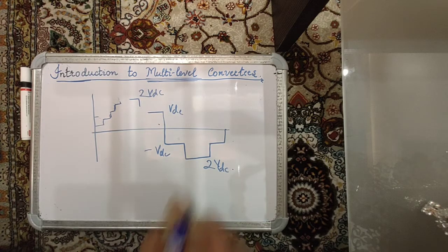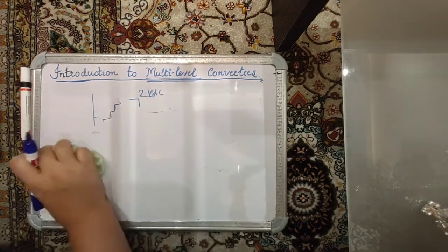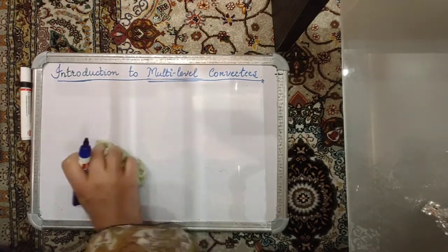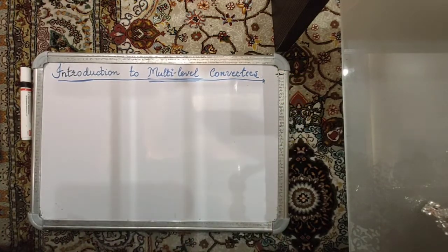So these kind of converters, you tend to use them in high power applications where you can afford to use a large number of devices as a one-time investment, as an initial investment, but you are drastically improving upon your running costs because you are saving on a lot of power, because you're not switching your converters at very high switching frequencies and you're not causing any power losses. Of course, they're expensive to begin with, but in the long term they give you more power saving benefits, without adversely affecting the waveform quality.